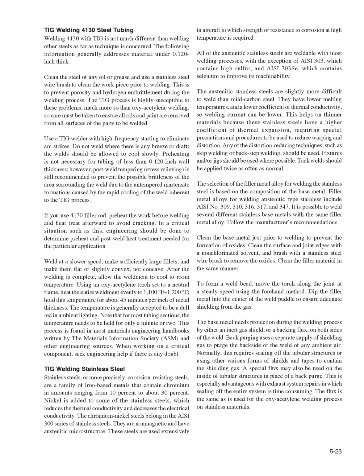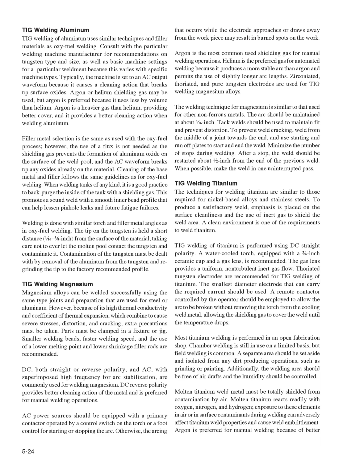The flux is the same as is used for the oxyacetylene welding process on stainless materials. TIG welding aluminum. TIG welding of aluminum uses similar techniques and filler materials as oxy-fuel welding. Consult with the particular welding machine manufacturer for recommendations on tungsten type and size, as well as basic machine settings for a particular weldment because this varies with specific machine types.